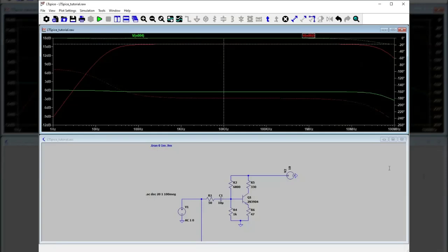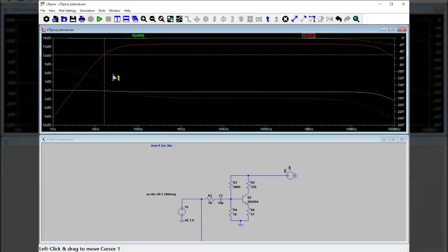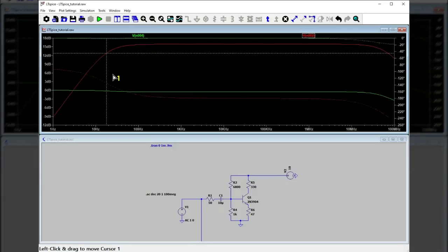Now, what can we say? Well, what are our 3 dB frequencies here? We're 15.9 dB in the mid band here, this big wide flat region. So let's go down at the bottom end. We're looking for 12.9 dB, 3 dB less than 15.9 dB. So at what frequency are we 12.9 dBV on our output? Now let's see. There's 13.9, 13.7, 13.2, and 12.8.